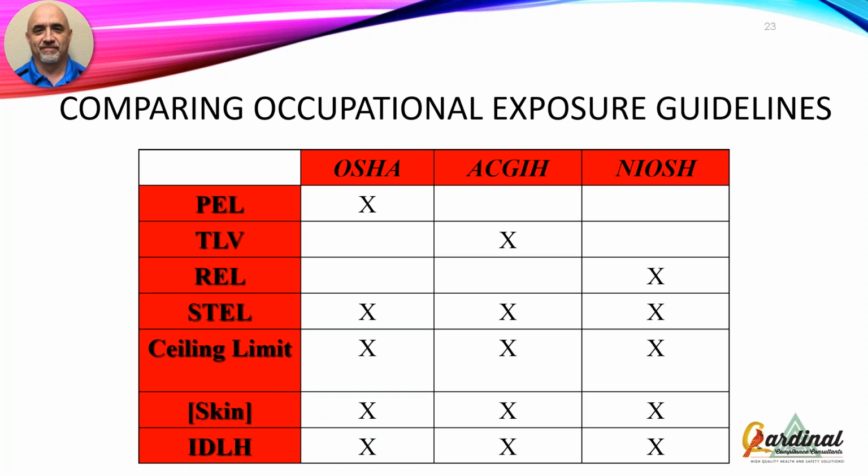40 years. And the reason I bring that up is to make sure that you guys understand that I see too often a company that gets an exposure above the permissible exposure limit, barely above it, and they have a bunch of knee-jerk reactions and they overreact because, oh, we can't go over the PEL. Well, you're right, you shouldn't go over the PEL. But from a practical standpoint, that is not something to always get excited about, okay? That's the equivalent of me pulling the fire alarm for a trash can fire, okay? So my PEL and my threshold limit value are both 8-hour time-weighted averages, 8 hours a day, 5 days a week, 40 years, all right?